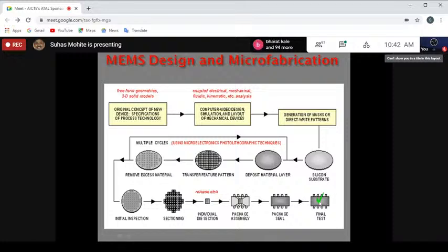So the sensor will be sitting inside this. The mechanical sensor will be sitting inside it, and it will be provided bias, input and output, and it can be made use of. It can be subjected through a small window. If it is a microphone, you can have an opening there too, so that the acoustic pressure can act onto it. So this is how the birth of a mechanical device with the appearance of an integrated circuit chip takes place.